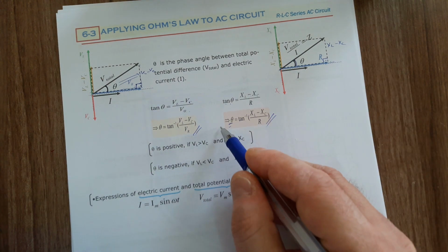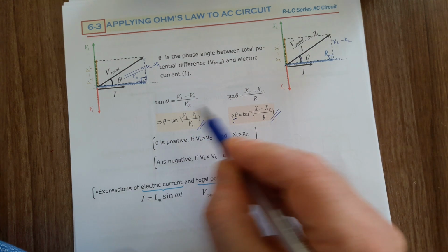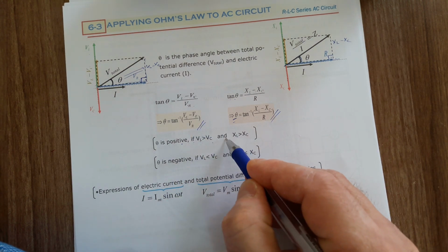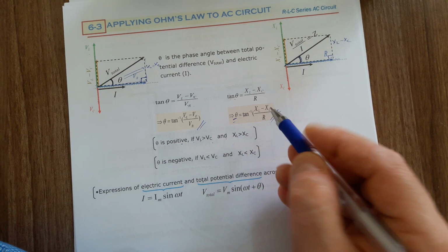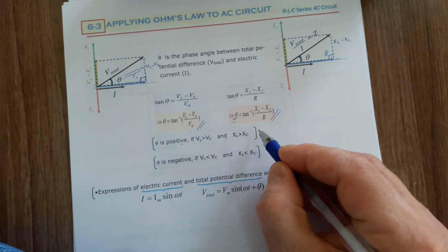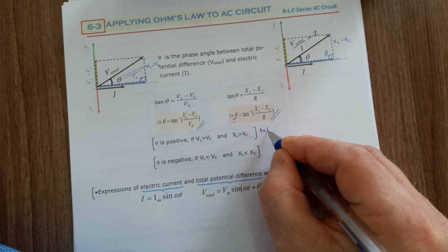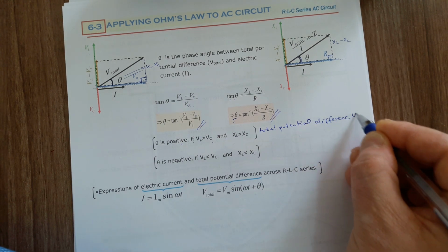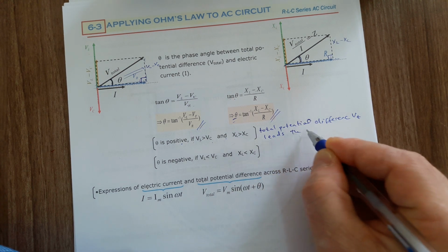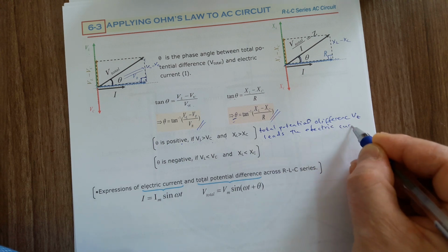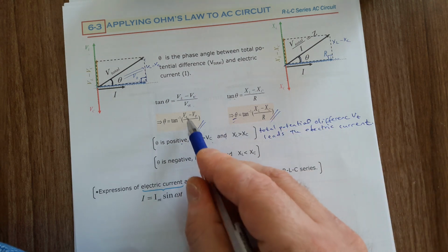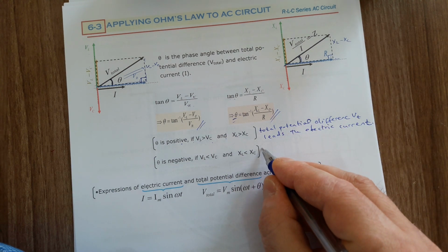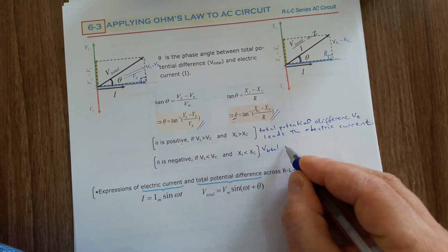If we look at these phase angle equations, theta is positive if VL is greater than VC or XL is greater than XC. Which means in this case, if it is positive, the potential difference leads the electric current. That is, the total potential difference, V total, leads the electric current. But if theta is negative, when? If VL is less than VC or XL is less than XC, which means theta must be negative. In this case, the total potential difference, V total, lags behind